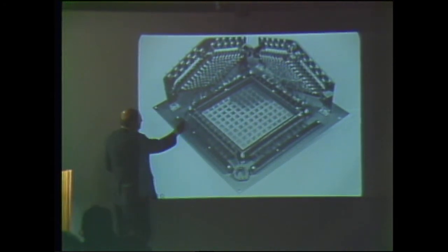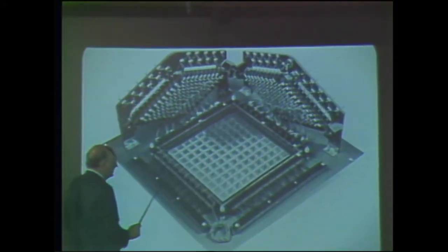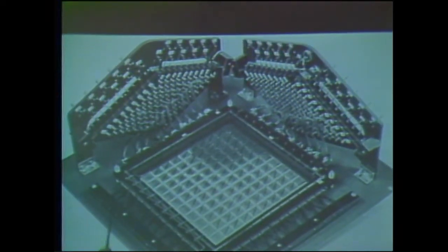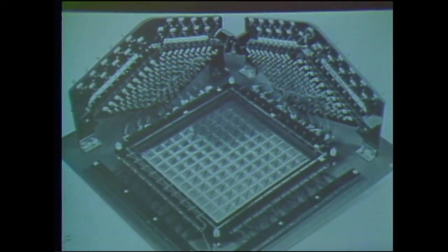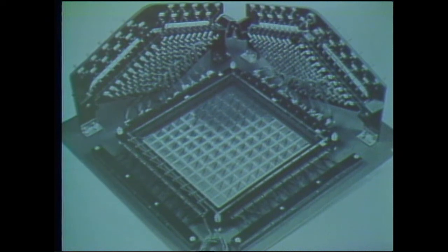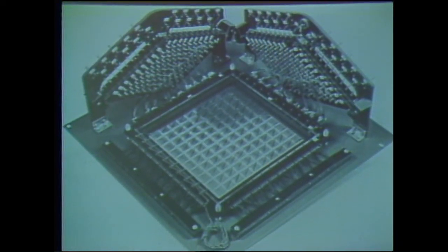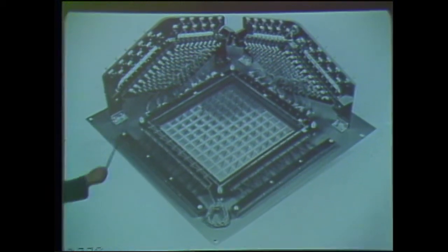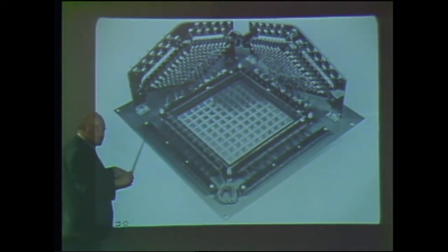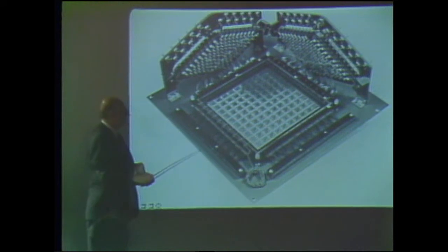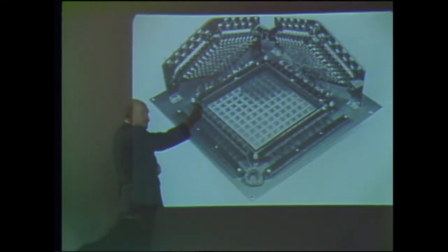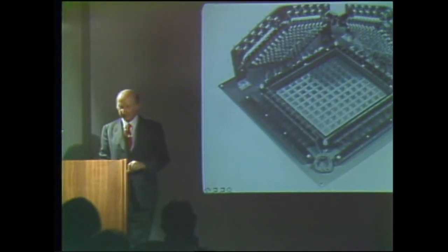And these things are magnetic switches, because even though this is 100 by 100, which is, of course, 200 leads and much less than 10,000, nevertheless, 200 is a big number if you have to drive each one by a tube. So we imagined a magnetic switch, which was also based on coincidence, so that it reduced it to 10 by 10 instead of 100.